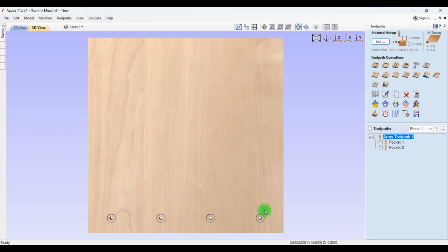of the spoilboard. So the next step I want to take is actually to create a surfacing toolpath so that I can level the top of the spoilboard so that I know that it's 100% perfect without any ups and downs in it, that it is level so that any piece I put on it is going to be the same regardless of where it's positioned on the spoilboard. So we'll jump into that now.